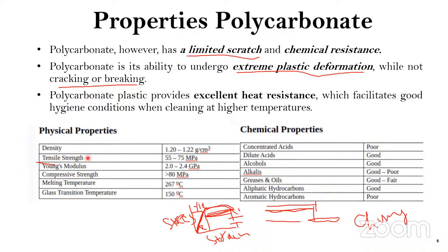Young's modulus is nothing but stress by strain, and it is the stiffness, called the E value, of the material. That is the elastic region only. Your Young's modulus will give you the value of your stiffness, and you can calculate it from this elastic region.